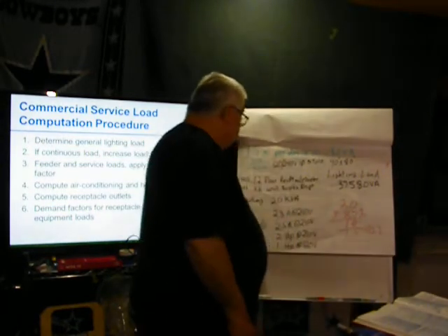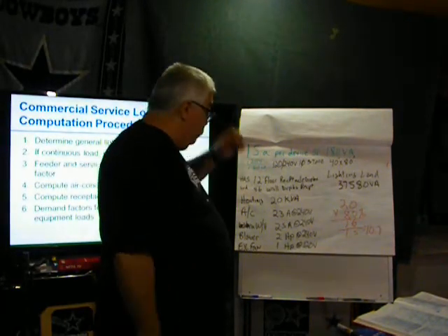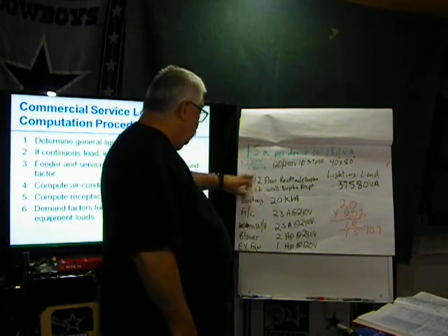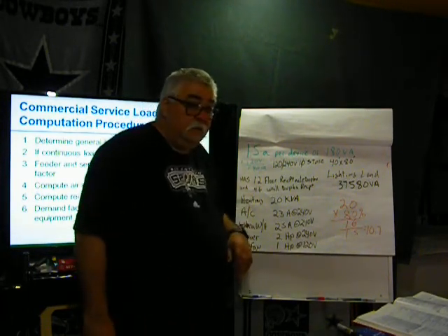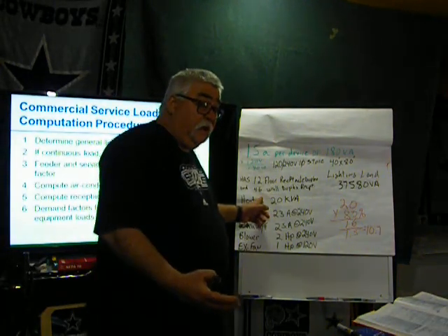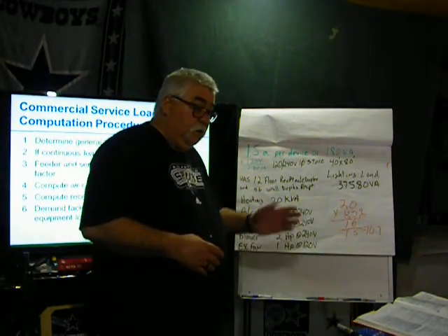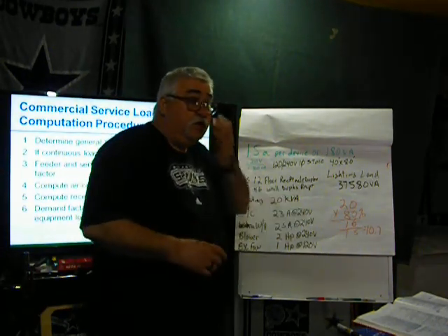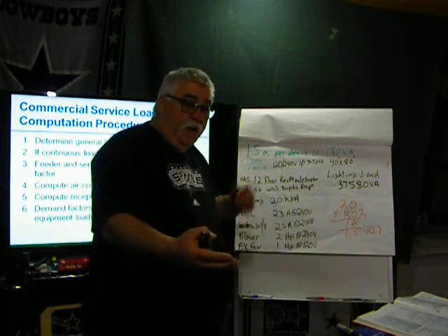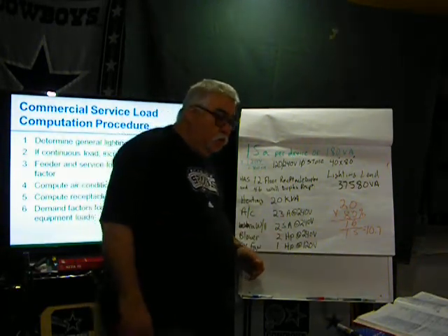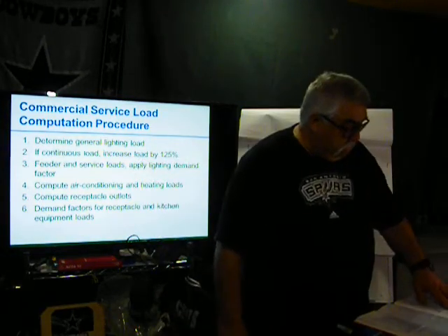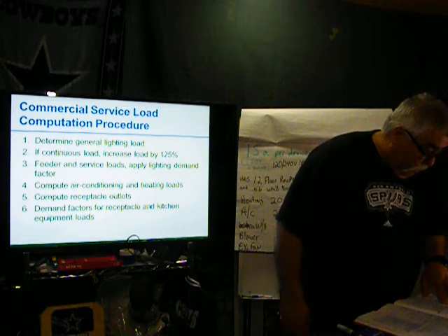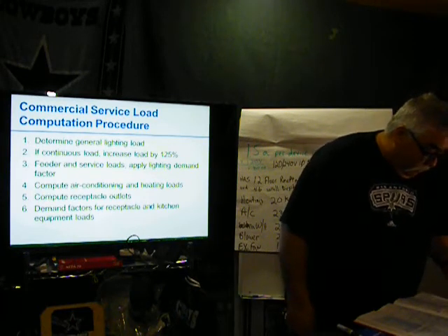Okay, so here, got some of your questions back already. So here, okay, I got 58 receptacles. Some of you didn't derate. If you're over 10,000, you derate the receptacles. So you get the first 10,000 at 100%. Anything over 10,000, you do it at 50%. Then you add that half to the 10,000. That is your new derated load. The sign lighting, 1200 VA minimum, section 220.14(F).